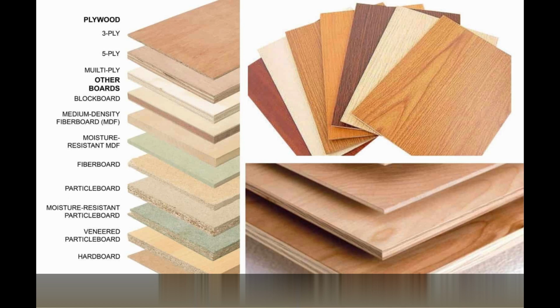The common dimension of this is 3 feet 11 inch by 7 feet 10 inch, or the slightly larger empirical dimension of 4 feet by 8 feet. Plies vary in thickness from 1.4 mm to 4.3 mm. The number of plies, which is always odd, depends on the thickness and grade of the sheet.